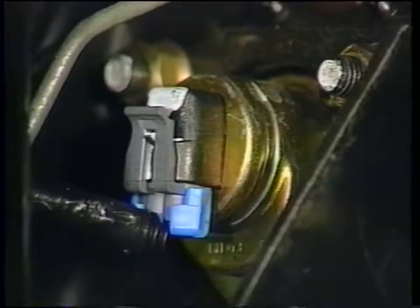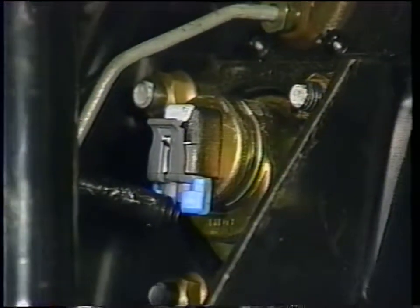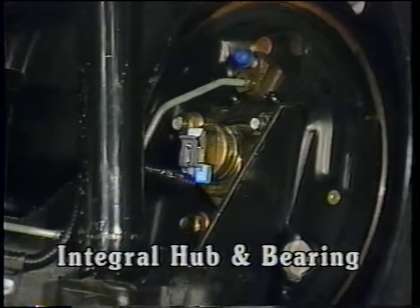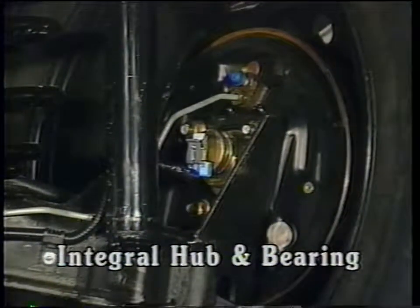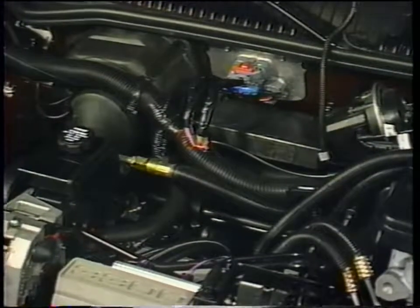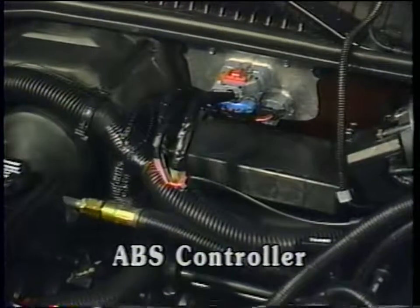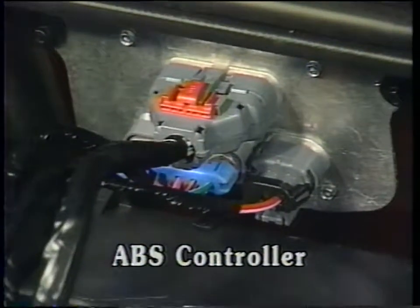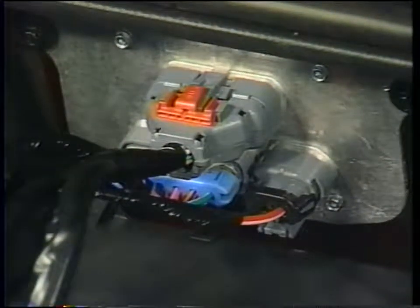The rear wheel speed sensors and sensor rings are located inside the rear wheel bearing and hub assemblies and can only be replaced as a complete assembly. Rear sensors are also non-adjustable. The brains of the Delco 6 ABS system is the electronic controller. It is not serviceable and must be replaced as a complete assembly. You'll find it located on the firewall in the engine compartment.